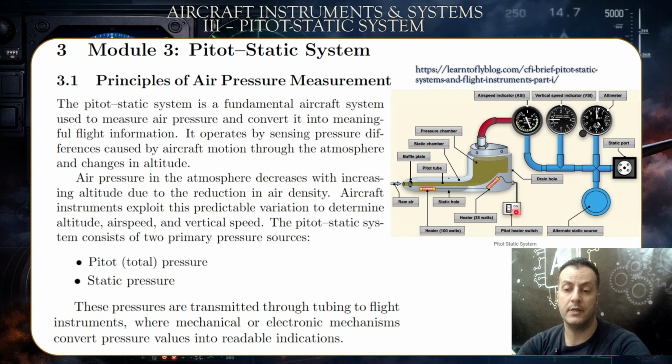It is necessary in order to prevent icing conditions. Otherwise, the icing would lead to the blockage of the tube. So the air would be constricted, which would lead to unreadable or erroneous data, erroneous airspeed measurements, which would affect the three of these instruments, especially the ASI.